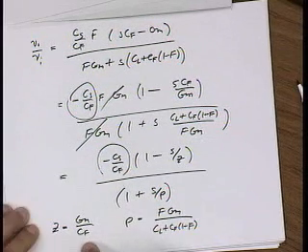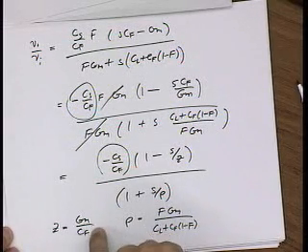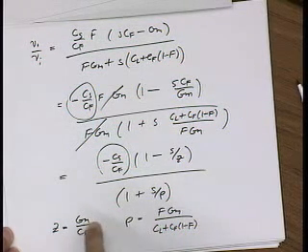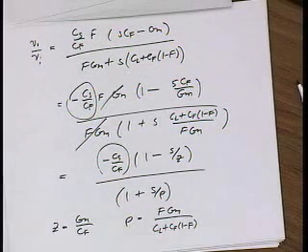Well, yeah, because there are two paths to the output. There's the CF path, and then there's the GM path. And at this frequency, the current going through CF is actually GM times the input voltage, which is the same as the GM path but with opposite phase. So they cancel each other, and the transfer function has a zero in it.